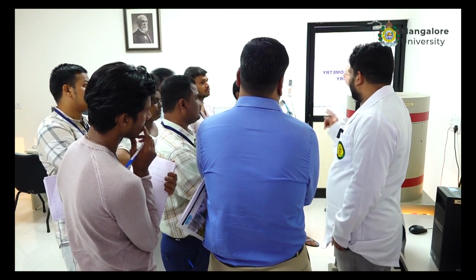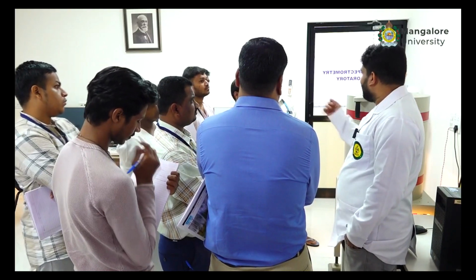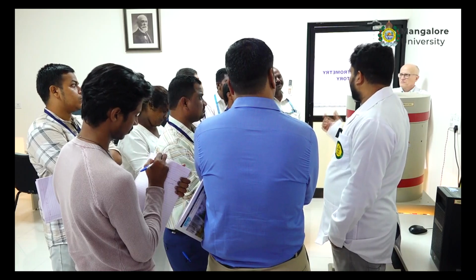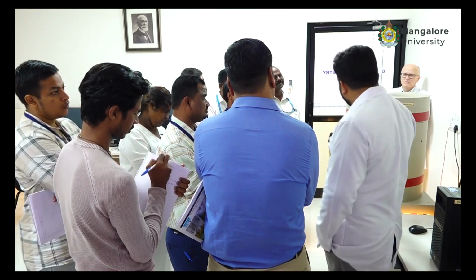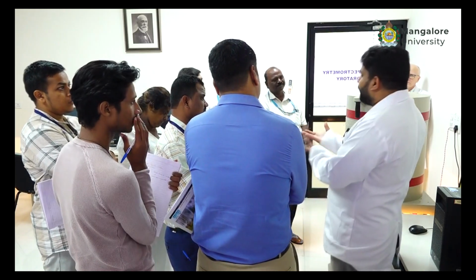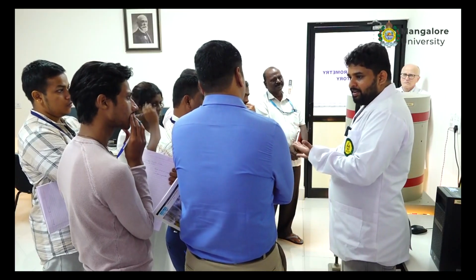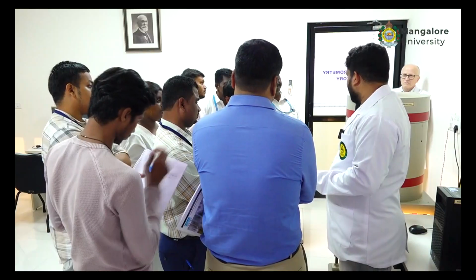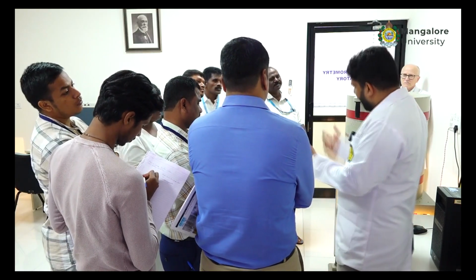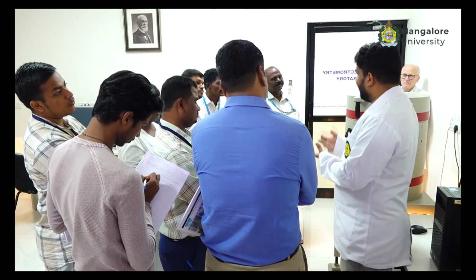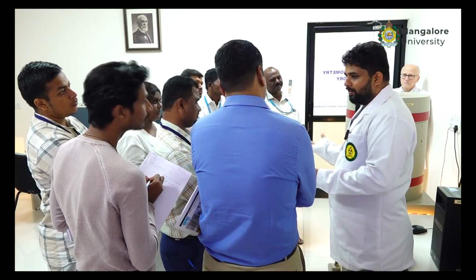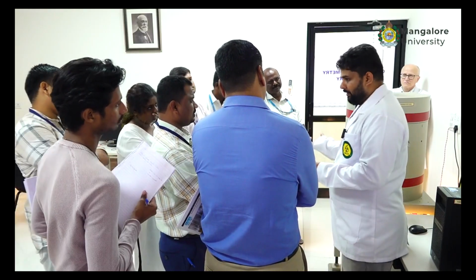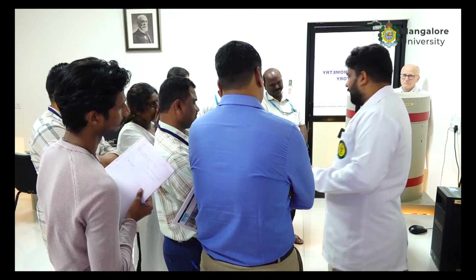Yes. A semiconductor is very sensitive to temperature changes. If I keep it at room temperature, a lot of thermal electrons can be generated. That will contribute to your signal. Then you cannot distinguish between what is your signal and what is your noise. So that is why we have to maintain a constant temperature. A semiconductor acts like a conductor at room temperature, and it works as an insulator at 0 degrees Kelvin. So that is why we keep it in liquid nitrogen.